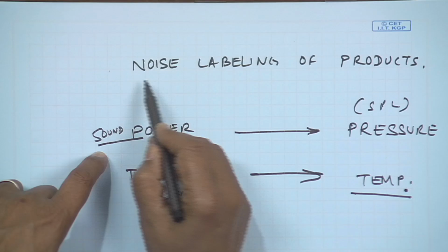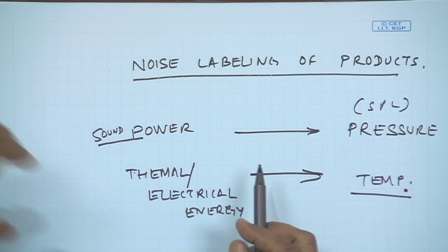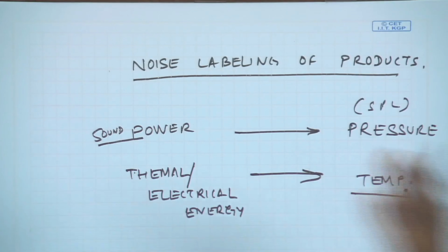Right? So, instead of measuring the sound pressure level of a machinery at a given distance in a given condition, it would be better if I knew the sound power of that machinery. I would specify a 100 dB sound power level ceiling fan or blower and so on. So, that is inherent to that. Suppose today I want to buy a refrigerator for my kitchen, and I would say the sound power of that refrigerator should be only 60 dB.